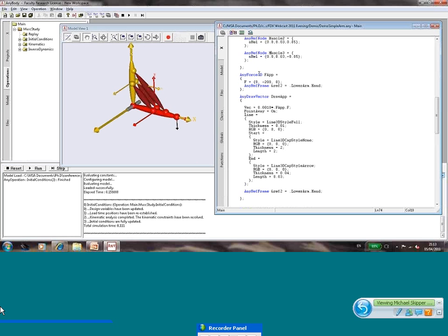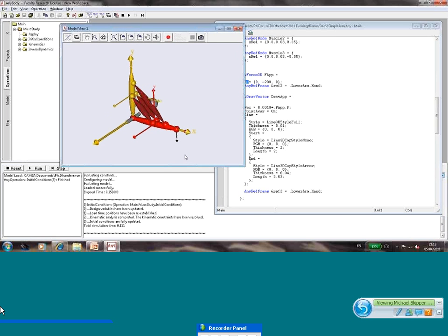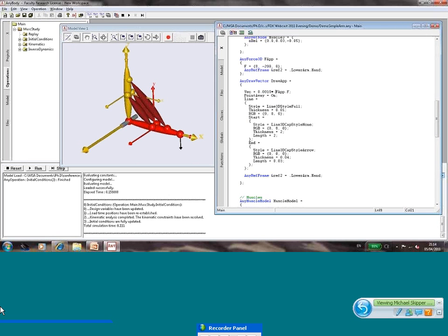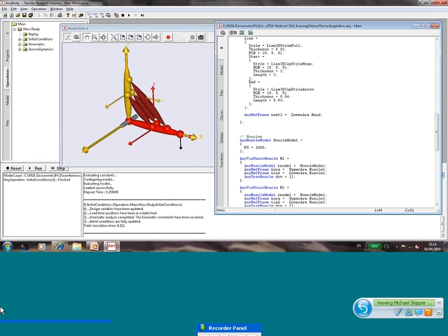This is a force applied at some point with 3D coordinates, and it's a force F here of 200 Newton in the minus y direction. If you go to Model View over here, you will see that the black vector is pointing in the negative y direction in global coordinates. So this is where our applied load is. Skip the next piece, this is just the drawing of this particular vector. Then we get to our muscles.